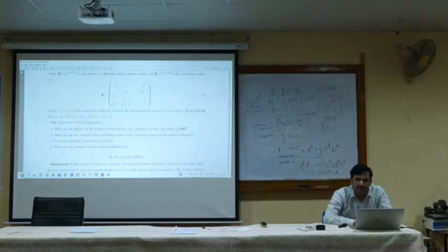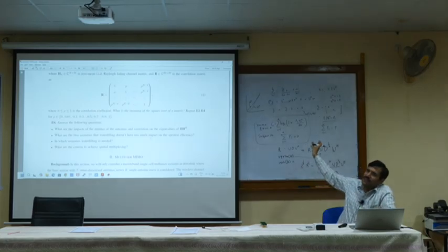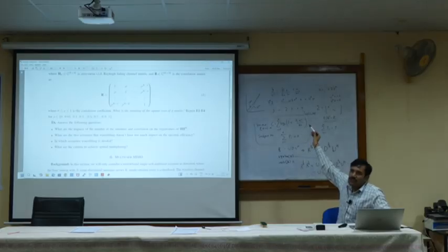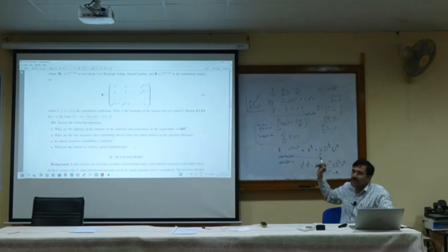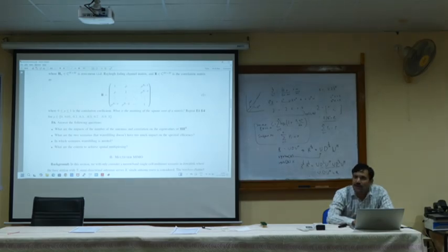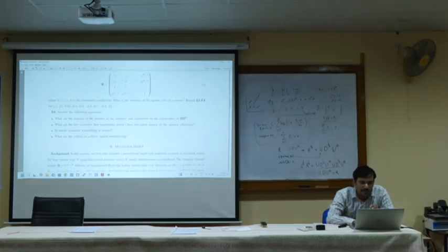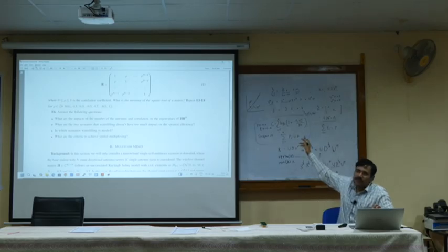Water filling doesn't have too much impact on spectral efficiency in two scenarios. One is the high SNR regime. In the high SNR regime, equal power allocation is equal to water filling. The second scenario is based on correlation. If we have too much correlation, water filling will also not help, even if you allocate more power. So in which scenario is water filling needed? In the low SNR scenario.